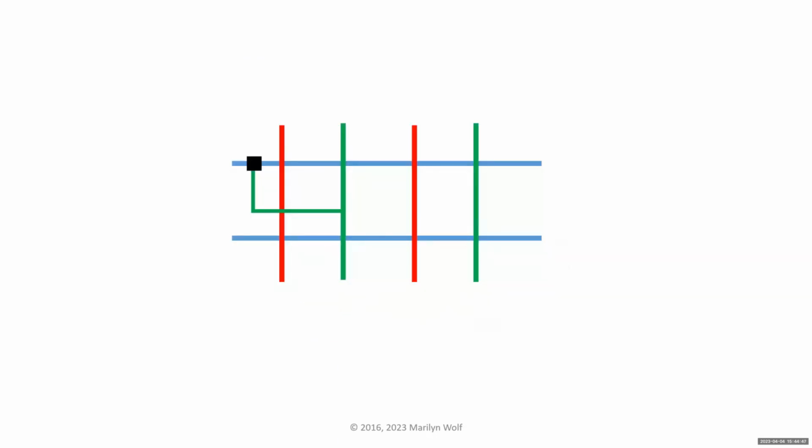So here is a stick diagram, a simplified layout of a section of one of these PLAs. The blue lines are metal lines that are running through the middle, in this case, horizontally. So this would be the AND plane, okay?